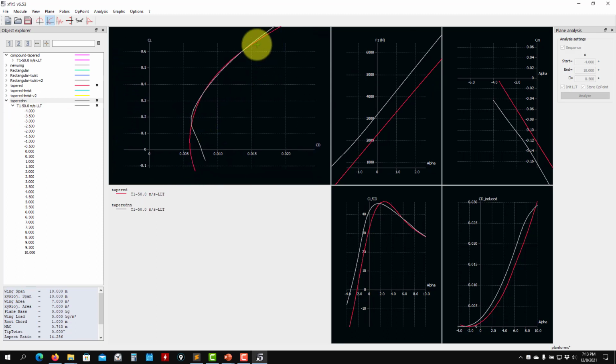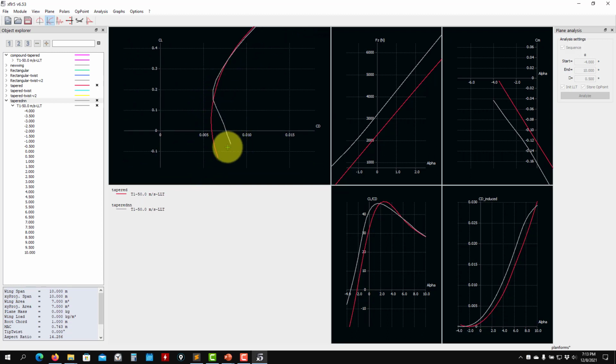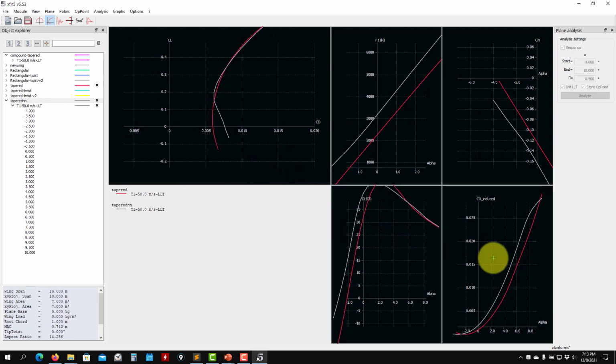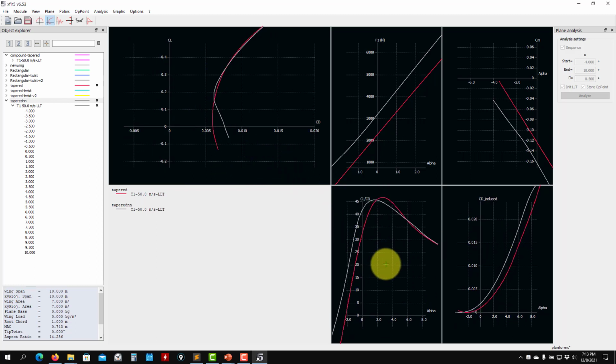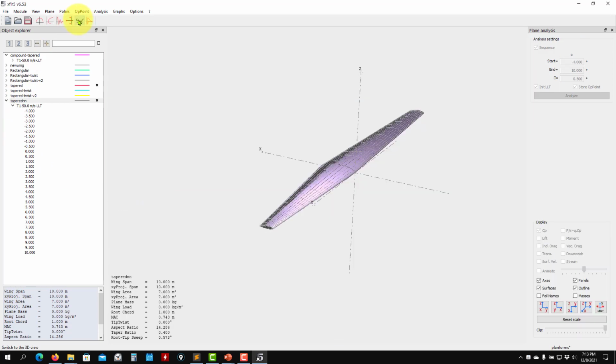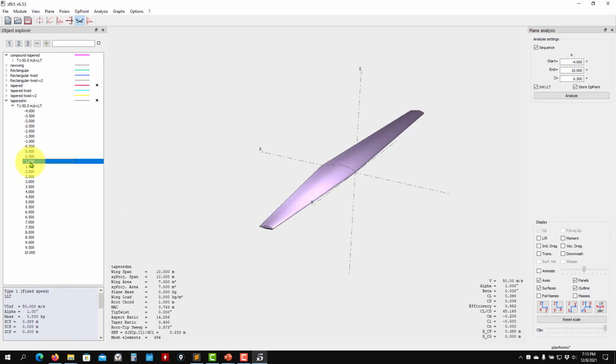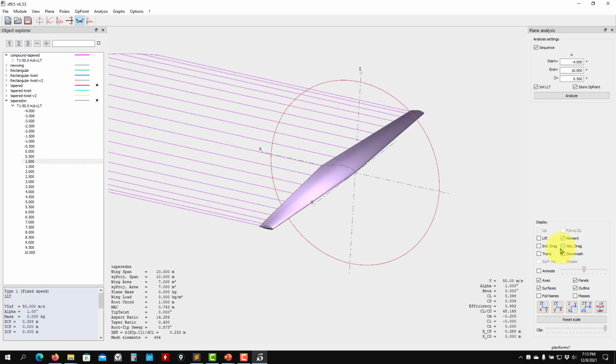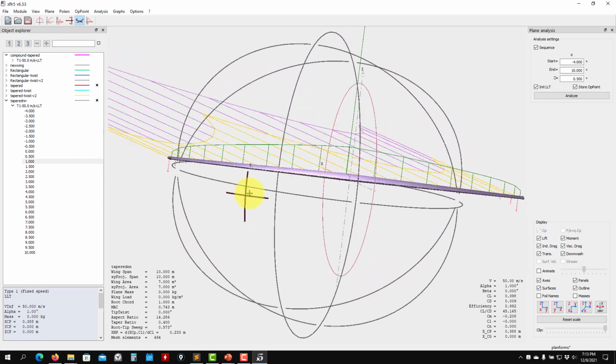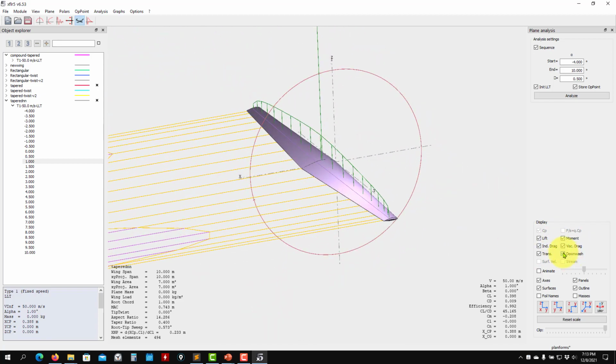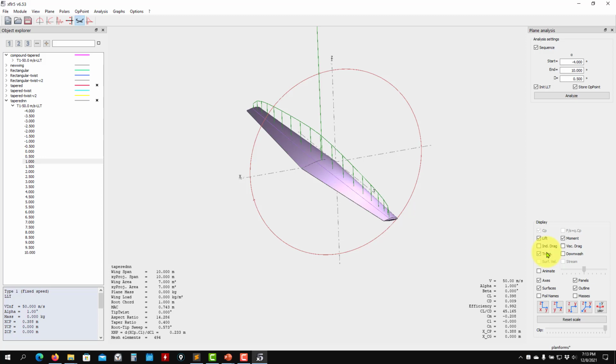For instance, you see that with this airfoil, here you can see this is a drag bucket, and you see we have the influence here. Also remember that you can visualize like this using the LLT. You pick an angle, and then you can select this option, but this is just visual. This is by no means a direct representation. So you can do it there as well.